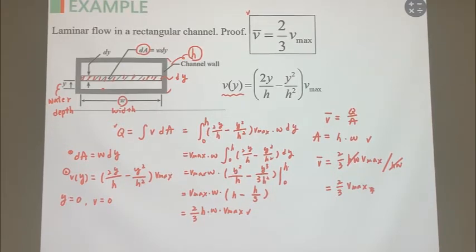Okay, so if you don't remember or you forgot anything about these formulas, you can derive the formula by yourself, right? You just base it on the Q, and then you know the A, and then you follow these definitions here, so you know how to calculate the mean velocity. But right now I tell you, if you can remember and keep in mind, for open channel water flow, always follow this relationship between the mean flow velocity and the V maxima.